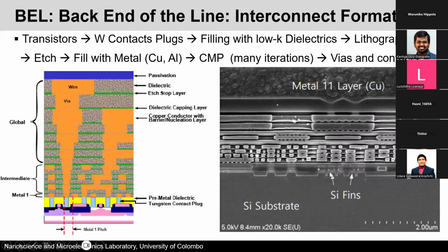But then what actually happens is, on top of all these layers, you can see the metal interconnects and vias. So that's what you see here as well. You have a MOSFET here, source and drain connections. These are tungsten plugs, and then connected to that are the metal lines going into the screen, and also in the other direction, right?